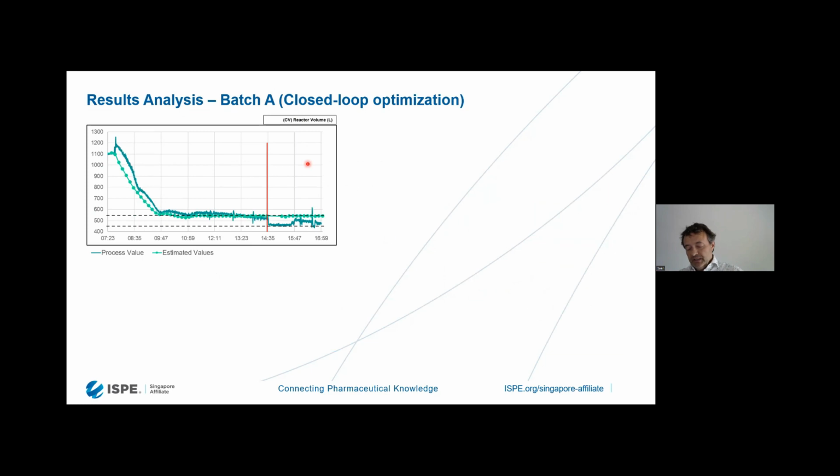We had some deviations at the beginning, which was a result of foaming, which the sensor thinks is a significant increase in volume, but it's only foam. The prediction errors stayed within the validation standard.